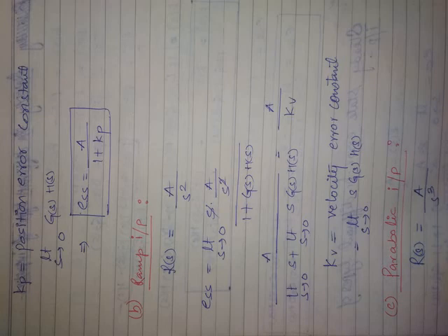Take for example that level control system only. In a level control system, we had controller, control element, plant and measuring element. If you take the plant, only plant having inlet and outlet, we have written one transfer function of that plant with input as Qi, output as water level.